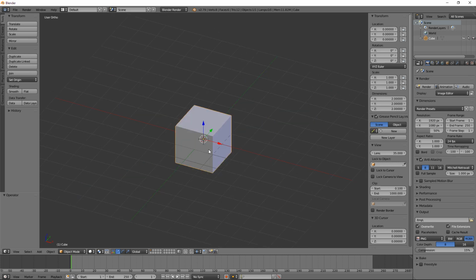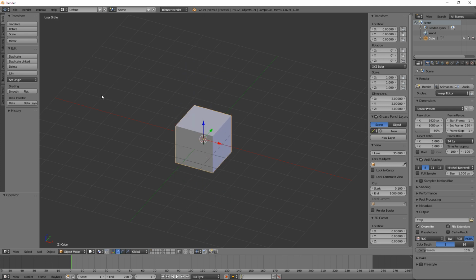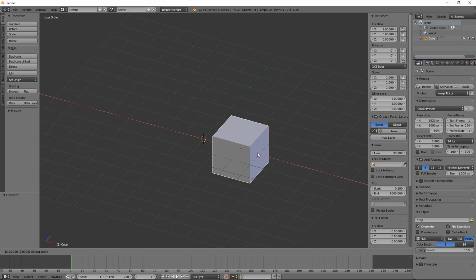The other thing you can do is while you've selected that object, I can press using the left button, grab any of those points, and do the same exact thing. Cool, huh? Rotating. I'm rotating in a crazy way, but I could also rotate with R, press Z. Now I'm rotating in Z. Lock it down to Z. I can further control what I'm doing, whether it's moving or rotating or anything, by holding down Control, and it does this tap, tap, tap kind of thing. You can see that better if I grab with G. I'll press X to move, and I'll hold down Control. See? Kind of jumps around.